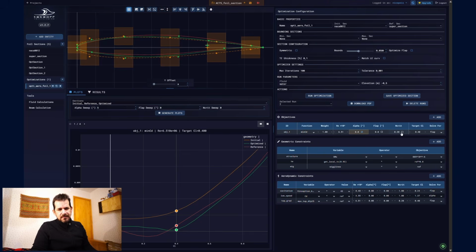And also, as this NCrit value is sometimes a bit arbitrary, we also want to play around, and we're going to say I want to be around 0.1 and 0.5 with 3 points also. So we'll have some kind of robustness around our optimization. We're not optimizing in a single point, but a little bit around this optimal condition. So let's see where we go with it.